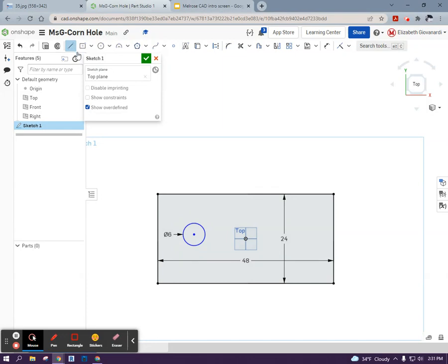And now I'm going to use what's called a construction line. We've talked about these, but they're like helper lines. So if you click on the line tool and then you toggle this to be a construction line, I'm going to just draw a line across here and have it go from one end to the other, so you can see the constraint coincident is the first one that appears there, and that is because it's saying that when I click down, the endpoint's going to be coincident to that bottom line. So that's great. So now I'm going to hit the L tool to end it, or you can hit escape. And what that did is it allows me to have a line on which I'm going to put the circle.